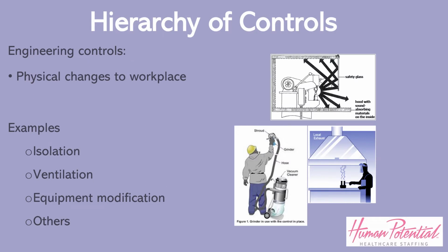Engineering controls require physical changes to the workplace, based on the following principle: if feasible, design the facility, equipment, or process to remove the hazard. If removal is not feasible, enclose the hazard to prevent exposure in normal operation. Where complete enclosure is not feasible, establish barriers or local ventilation to reduce exposure to the hazard in normal operations.